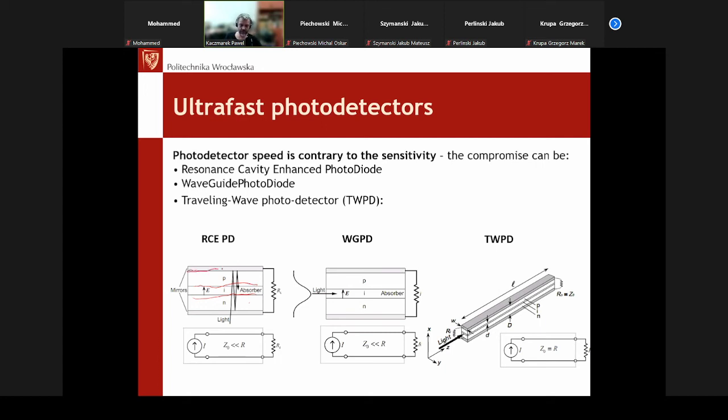So it means we have two mirrors forming some kind of Fabry-Perot resonator between them. Additionally, these mirrors can be made as a Bragg reflector, so they operate at one single wavelength. So it allows us to create a fast photodetector that is additionally quite wavelength sensitive. So this photodetector can be designed to detect only one single channel from WDM systems, for example.